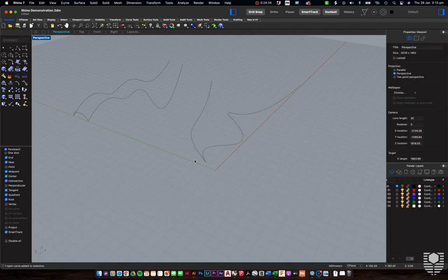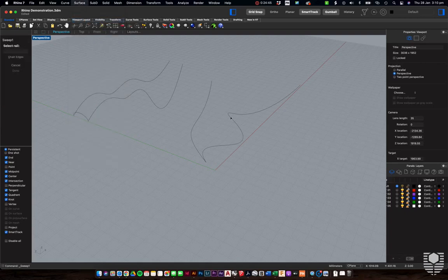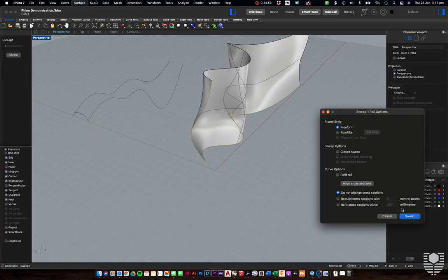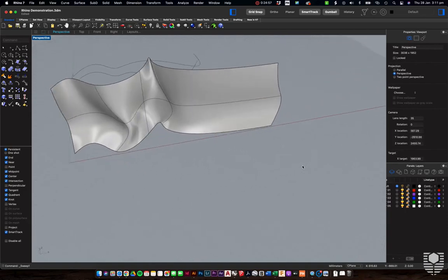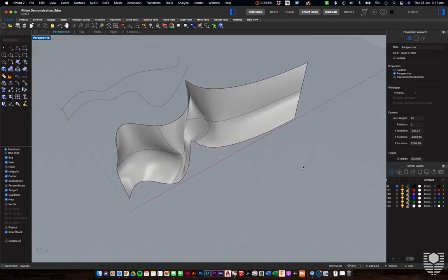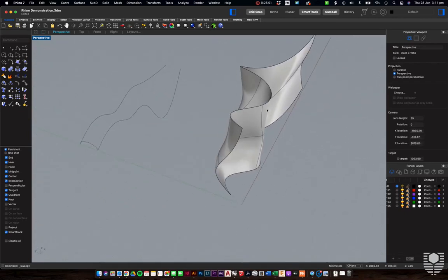All right, let's say you have a path like this one here, and you have a geometry, and you want this geometry to follow along this path. To do that, we use the sweep command. So in this case, we have one rail that we're sweeping. So we sweep one rail. We have the rail that we're trying to sweep, the cross-section curve, and then we press enter when it's done, and we're happy with those settings. We click sweep, and we see that the line that we had vertically upwards before is followed along with the curvature of this one here.